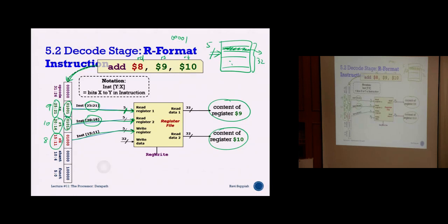And the last one here is your destination register, bit 15 to bit 11. That means after I finish the operation, I need to write back to this register, correct? I still need to do an add operation, and the result must come back to my write data here. After I complete the add operation, which we are going to look at now, that result must be written back to my RD, my destination register, and that is already specified as my write register.